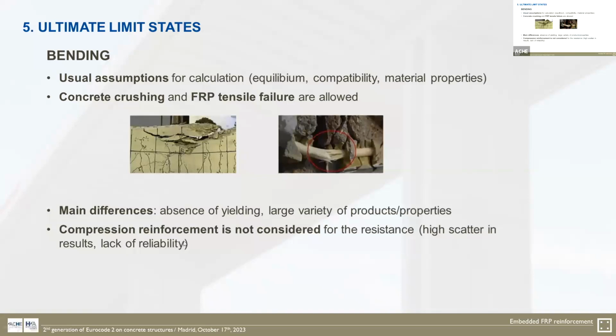Compression reinforcement is not considered for the resistance because tests have shown that there is a high scatter in the results. So finally, this means lack of reliability. And in the end, because it works under compression with this low modulus of elasticity, the contribution is quite low.